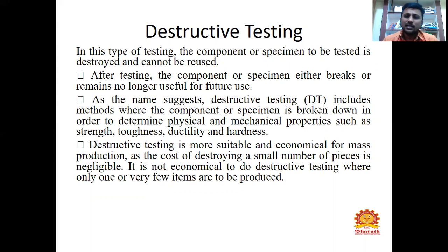Destructive testing is more suitable and economical for mass production, as the cost of destroying a small number of pieces is reduced. It is not economical to do destructive testing where only one or very few items are to be produced.